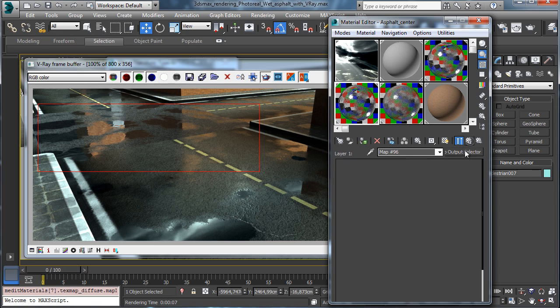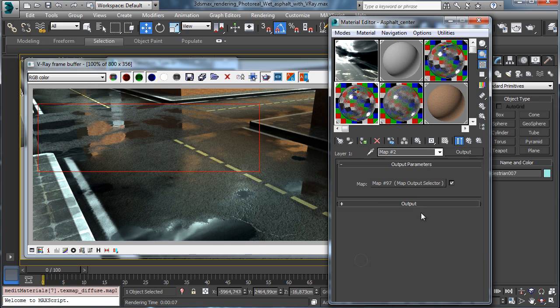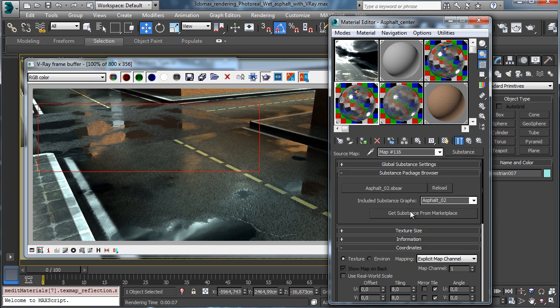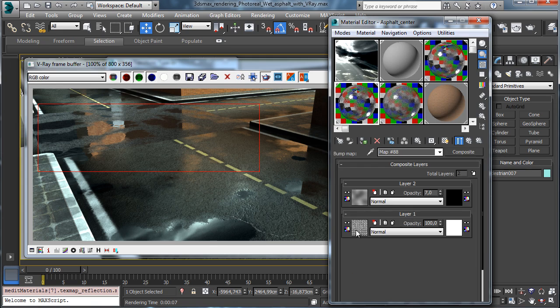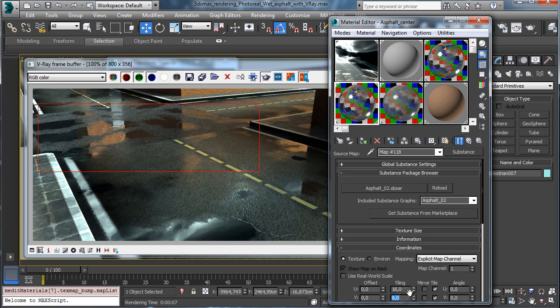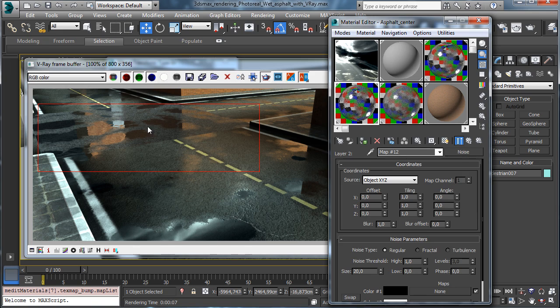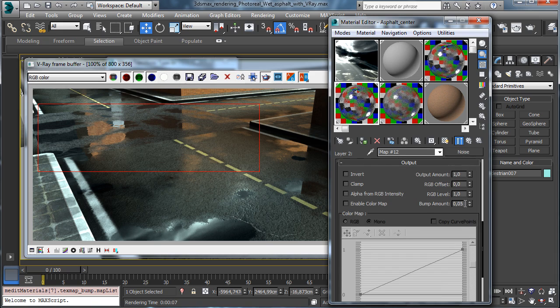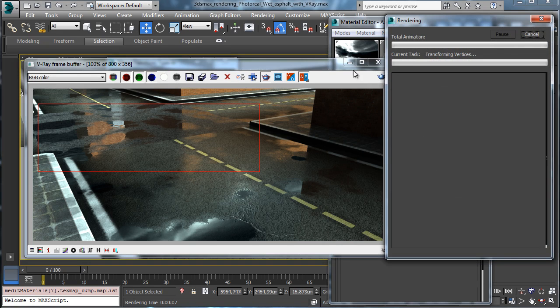Let's see if we are using the same map in other parts of the scene, and we are using it there as a specularity map. So 16 and 16, and we have to do the same for the bumping too. So we have there 16, 16, and you see that we have too much bumping for the puddle too. So let's go for, we have 0.05, so that's nice. Let's see if that's enough.